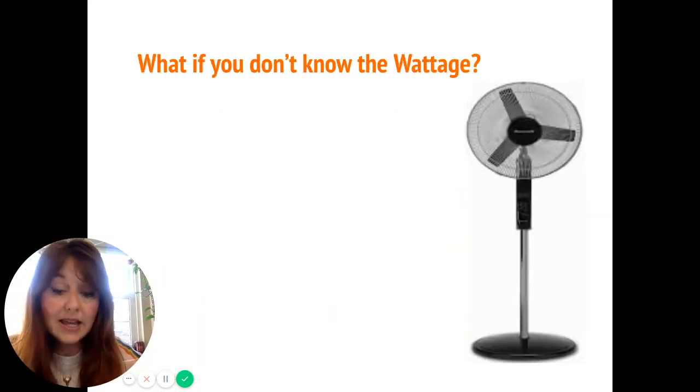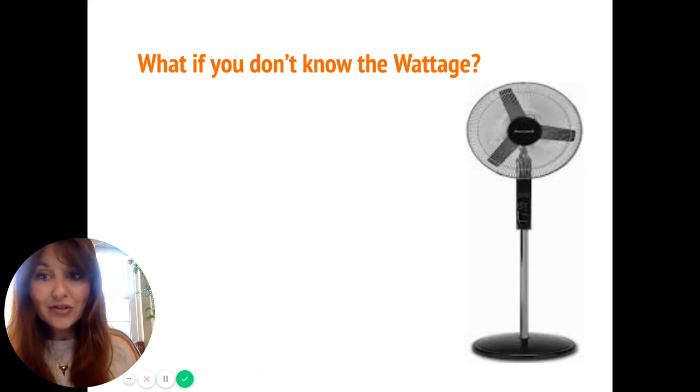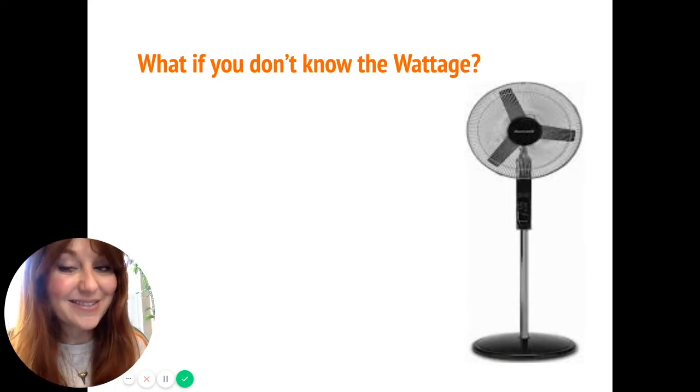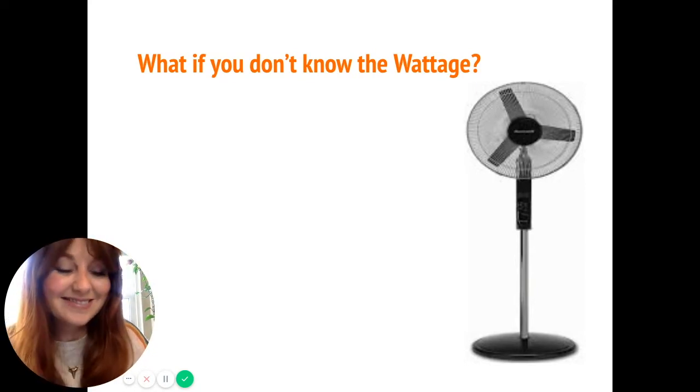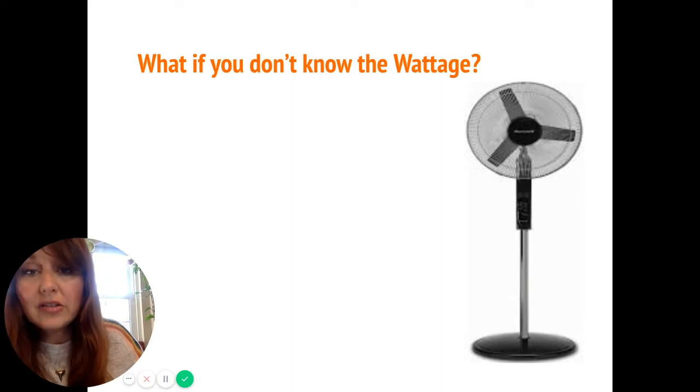Okay, last thing before I send you off to your lab: if you don't know the wattage, you can actually look at the amps, because remember, power equals voltage times the amps. You can look at the amps and just determine the wattage from there.